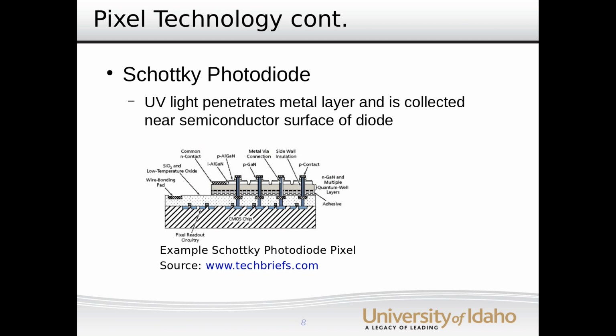However, Schottky diodes also have a higher leakage current when reverse biased, so you might have more noise associated with that. And there's also difficulties in processing Schottky diodes, particularly when it comes to photodiodes. There's been some anomalous behaviors identified in the electronic circuitry of these Schottky photodiodes.